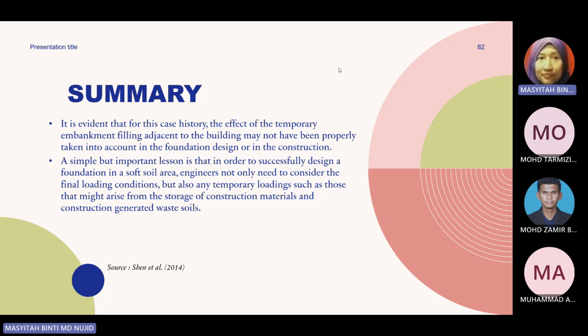Then you may have the soil strength before failure. Before failure is usually before construction starts, when they already have a site investigation report. So when you do back analysis in software, for example, there is a method we call the shear strength reduction technique. The shear strength reduction technique incorporated in Plaxis, the geotechnical software, can estimate the strength value during the failure. It can tell you what the value is. Meaning in the back analysis, we estimate from the failure back to the original one. So we see that originally the soil strength was high.